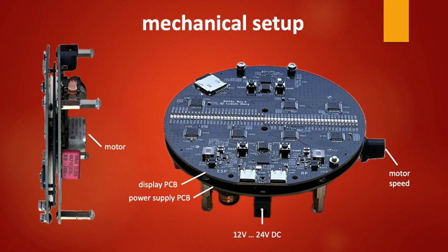In contrast to the first version of the display with monochrome LEDs, the color display uses SMD components only. This was the only way to achieve the necessary integration density. The circuit board has 4 layers. The 2 inner layers are grounding planes. I learned a lot about PCB design from the videos from Phil Salmony and Rick Hartley. I linked the videos in the description and can only recommend them. The display was produced in small quantities by a Chinese PCB manufacturer.